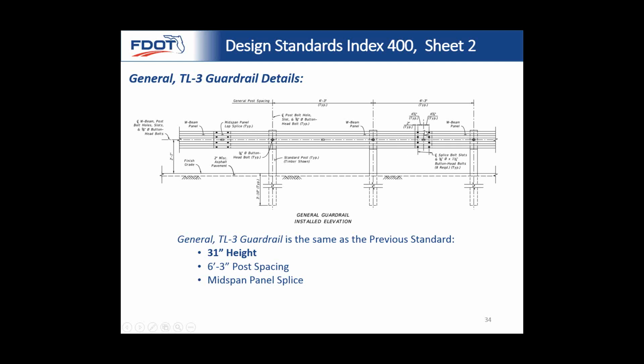Previous guardrail, a lot of existing applications, it's 27-inch height, and this splice right here is located on the post. So when you go to our new guardrail, you need to quickly transition to the new type of height and spacing. The height allows for increased energy absorption.